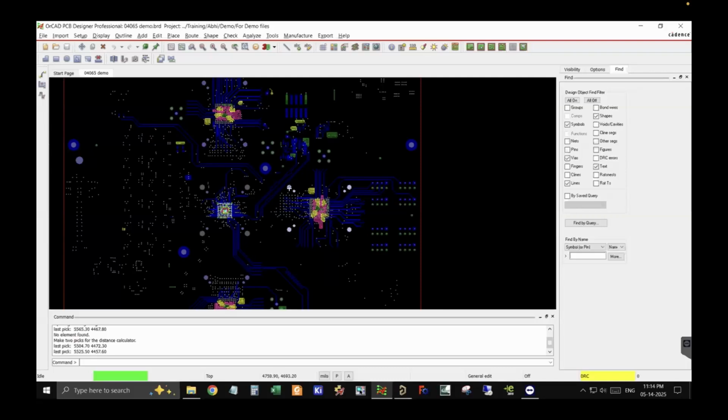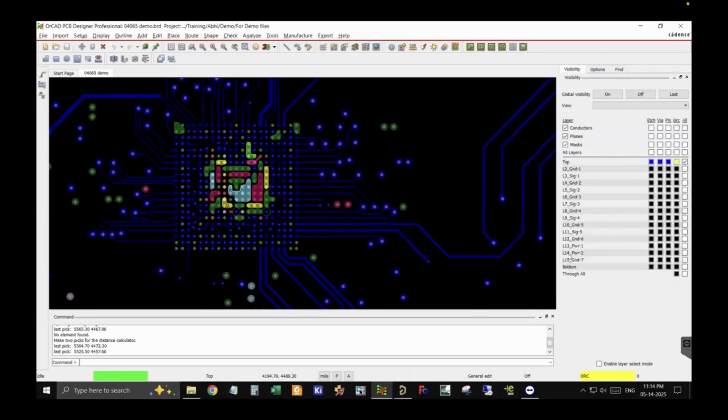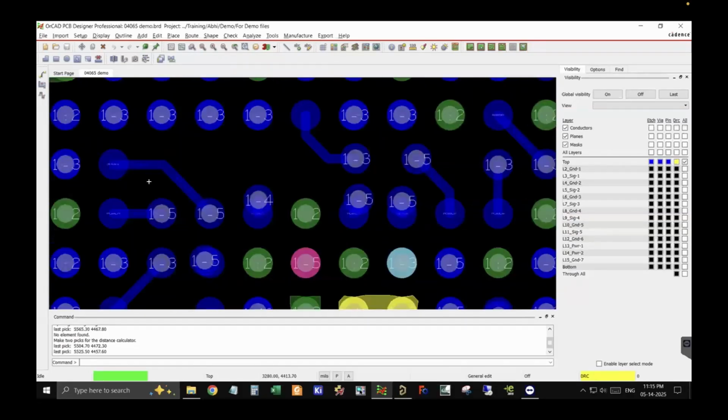One problem was created due to the sockets, because if this was a normal IC, we could have placed it much closer, but there are these holes over here. So we had to keep it slightly away, and that itself was taking around 150 mils. That created a problem for us, because we already had a length constraint, and due to this the constraint increased even more. So we tried to place them as close as possible. Then coming to this, this is again a 16 layer PCB, which is 95 mils thick. Okay, so I'll just show you the spacing that is available between any two pads.